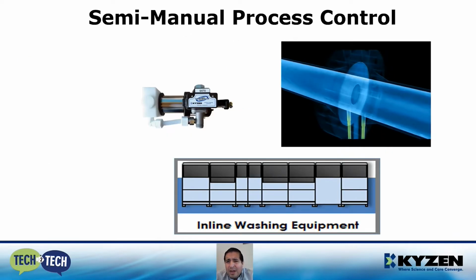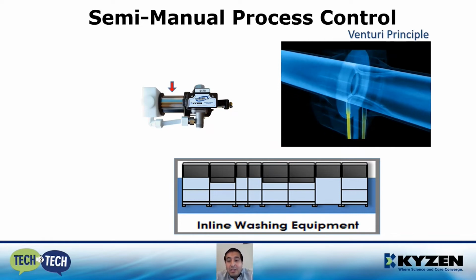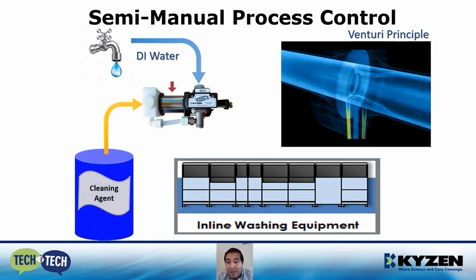The controller is a water-driven pump that uses the Venturi principle to drive a chemical piston pump that is integrated in the system, harvesting the pressure of the wash tank makeup water line to inject chemistry into the wash tank of your equipment. In other words, every time your equipment demands to refill the levels in the wash tank and it opens the water inlet, both water and chemical at a fixed proportion will begin to flow and refill the levels in your equipment.